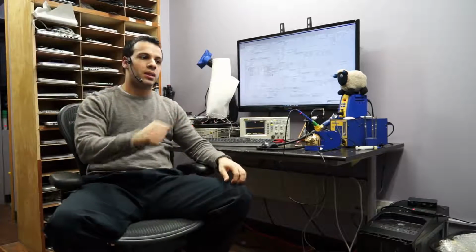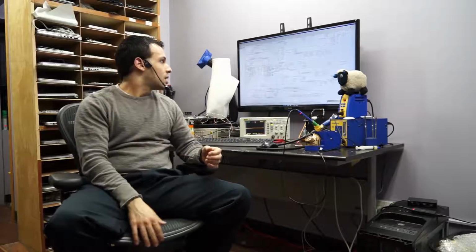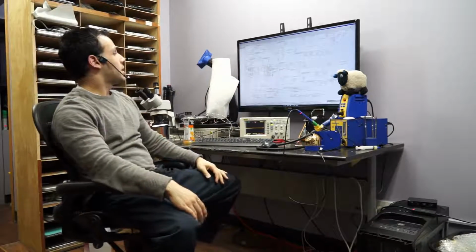So, point is, this is not simple. This is not just, oh, there's a fuse that goes to the battery. People will always ask, why don't they just design it simple? Why can't there just be a fuse on the charger and a fuse on the battery? That would make this simple. There already are fuses there. They never blow. They only blow if lightning hits it. There is a lot more to the system than just having a fuse. Don't you actually want your system to turn off if something happens instead of blowing up the charger? That's what the high side current sensing is for by the charger.